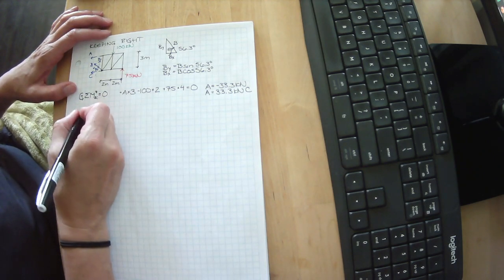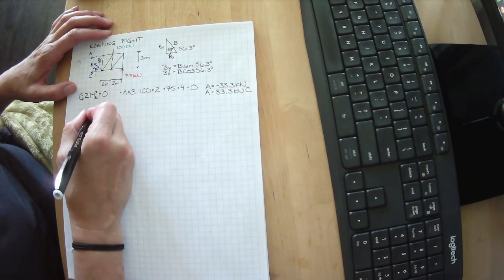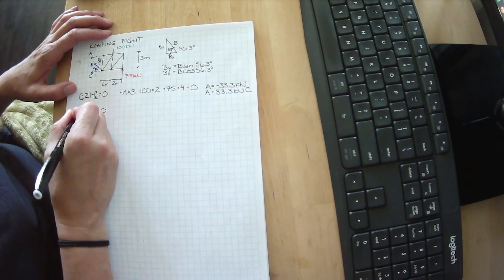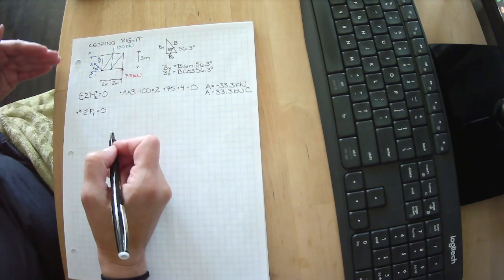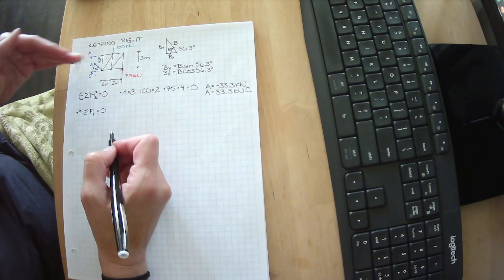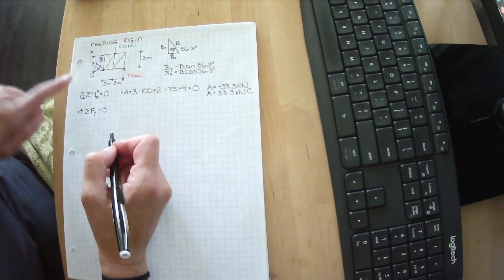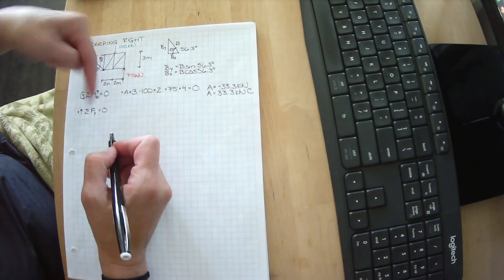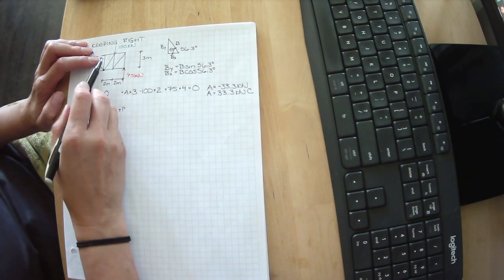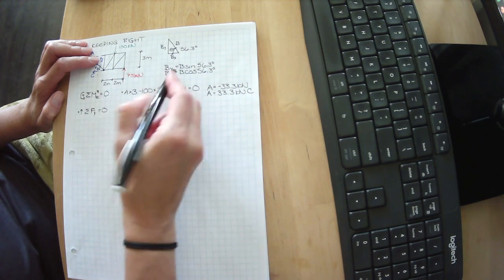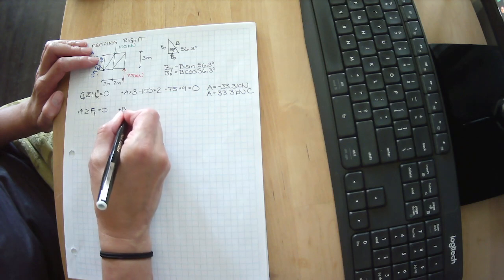Let's now try summing our forces in the y direction. So everything upwards is positive. A is in the x-axis, C is in the x-axis, Bx is in the x-axis. Sorry, those are all on the x-axis. I've got By, 175. So plus By, well, I'm lazy. I'm going to write directly, and instead of writing By, I'm going to write that as the placeholder for By.